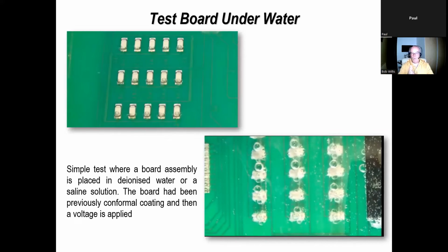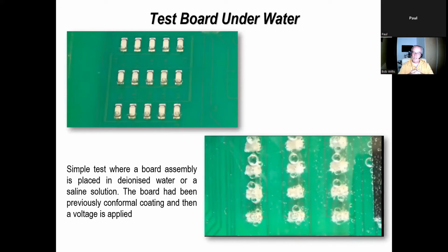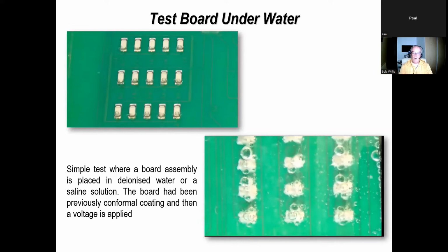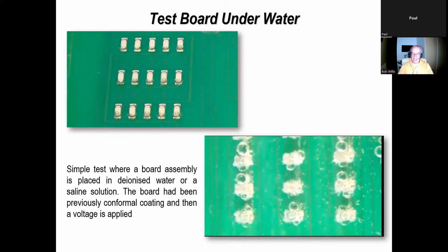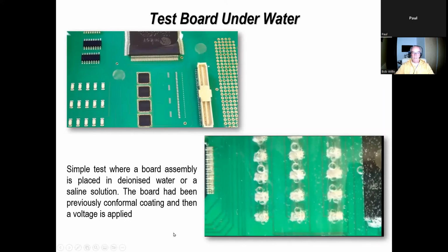These are on 0402 chip components, and you can see this nice sort of chemical reaction taking place. And I've done tests for conformal coating material suppliers where we've done this test and you don't see anything happening. So if you get the right combination of materials and thicknesses, and you put it in a bucket full of water with power, obviously, you don't get any reaction because all those surfaces are covered. There is an insulating body between all those surfaces. So again, it's just something else that hopefully is of use and assists you.